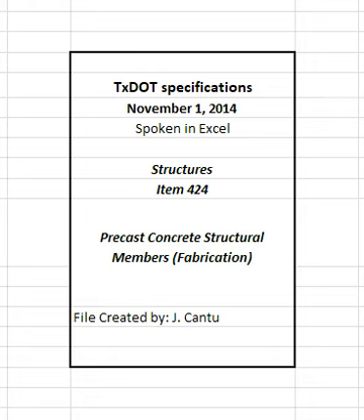4.2.7.2 Moisture retention curing. Moisture retention curing prevents moisture loss from the concrete. 4.2.7.2.1 Form curing method. Concrete surfaces in direct contact with forms that are left in place will not require additional curing methods unless cold weather protection is necessary. 4.2.7.2.2 Impermeable cover method.